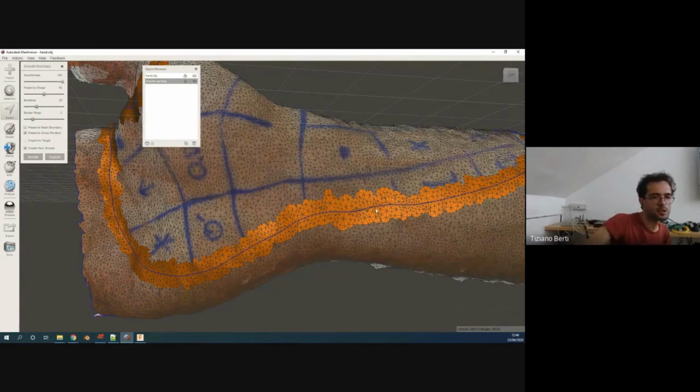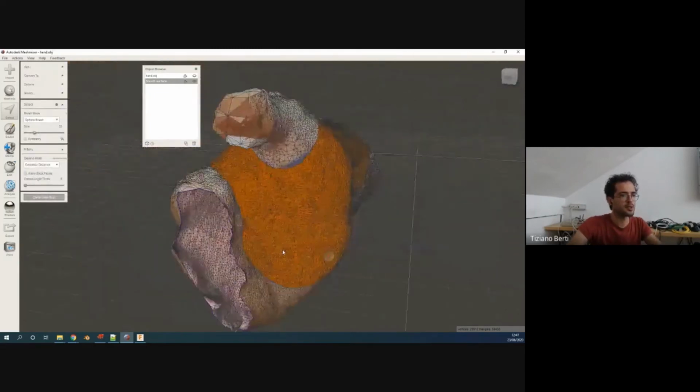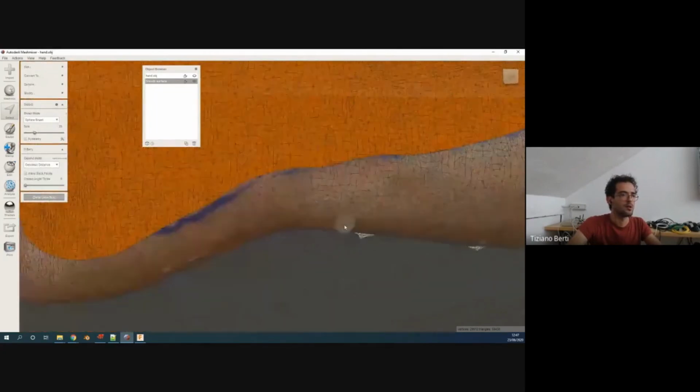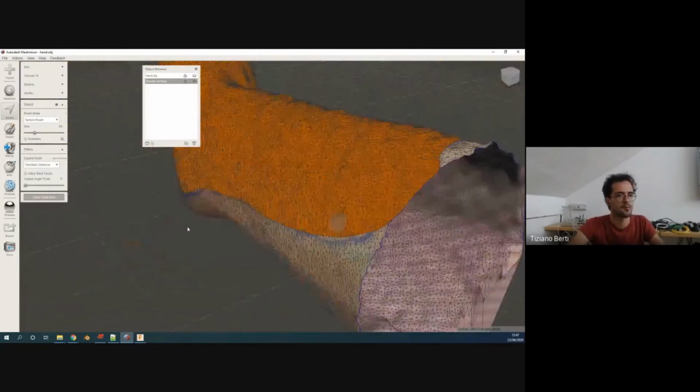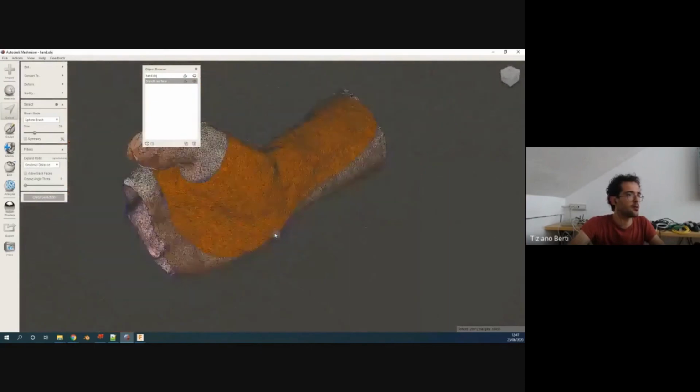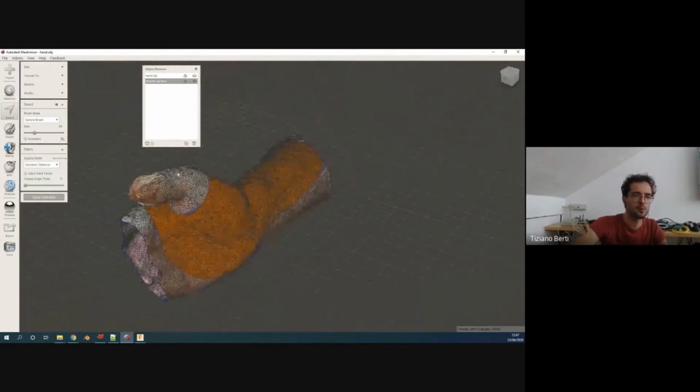This is a very powerful tool. It's not easy to find this tool on mesh modeling software. And we also have a preserve shape option, which is relaxing or keeping the shape closer to the original surface. But for the moment, we will keep it like this. So we accept the editing. As you can see, we still have the other part of the selection, but now the edge of the selection is much nicer. And right now we can choose to delete the part we don't need.